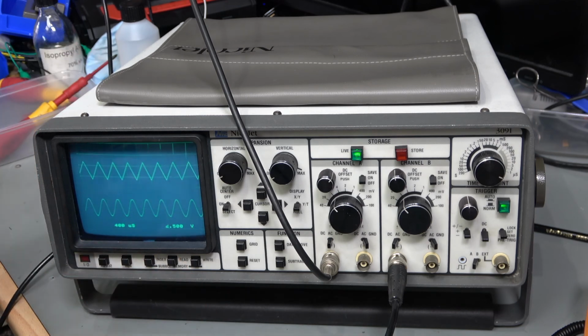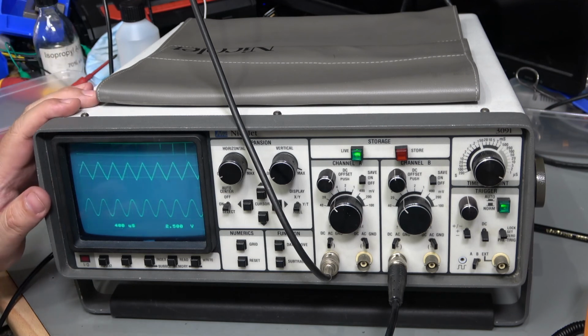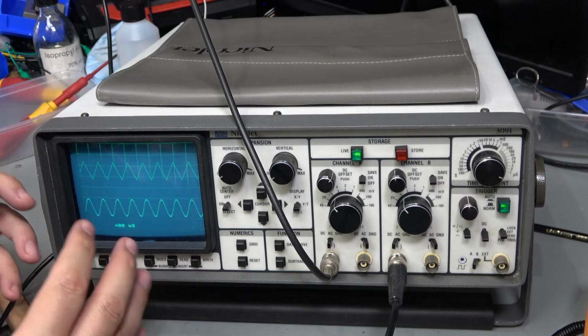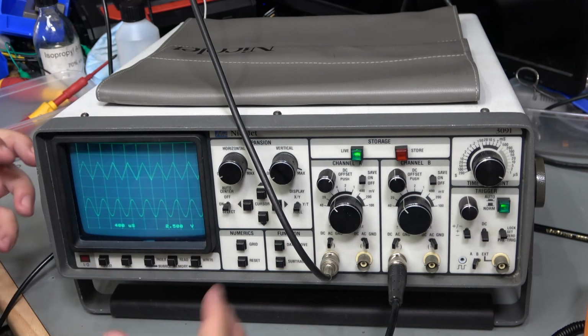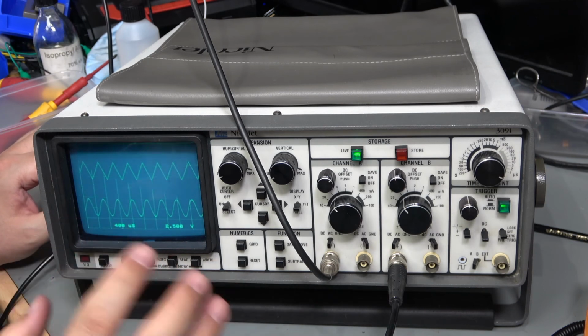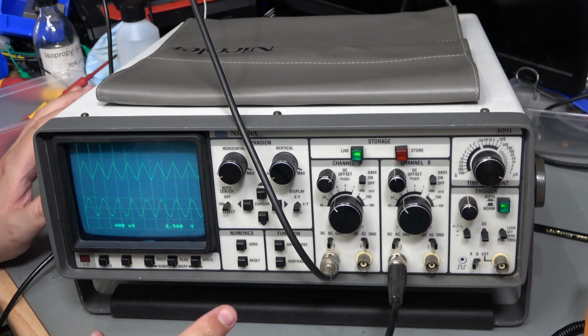and all was well. I also had a bit of a problem with the power supply in that it has an adjustable current cutoff, and this was cutting off sometimes when it started up, and I think that's just because of the initial surge charging the capacitors and things like that. So I've managed to find that and adjust it, so that seems to be stable now.